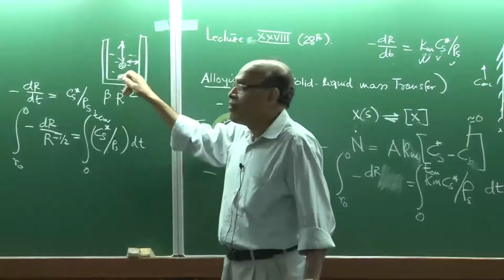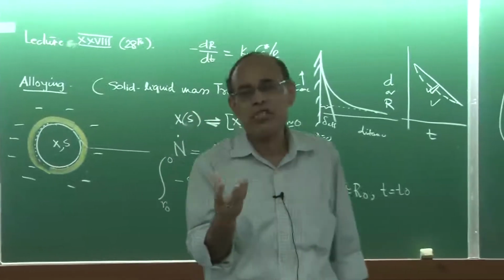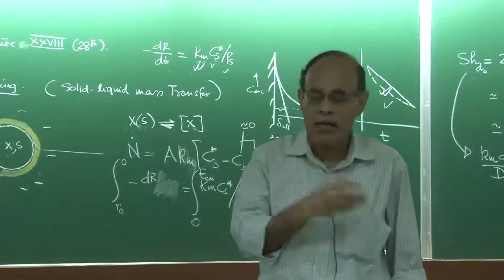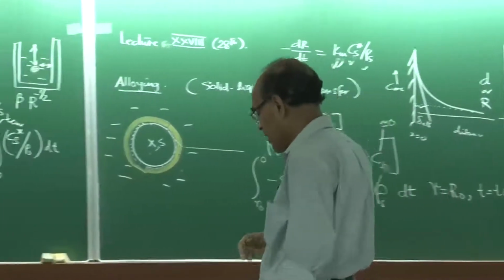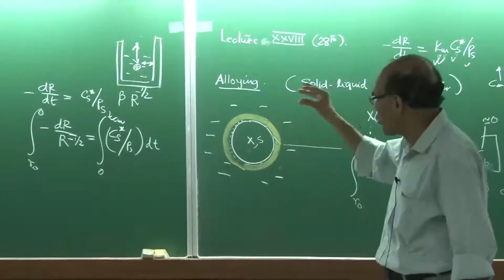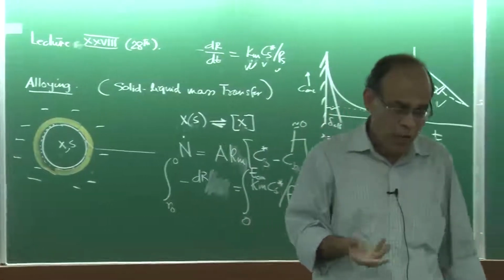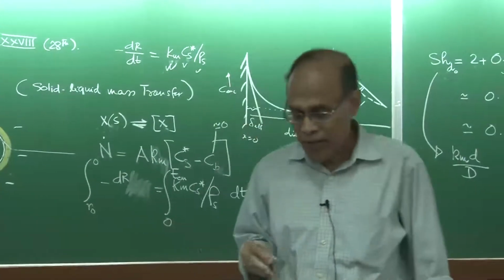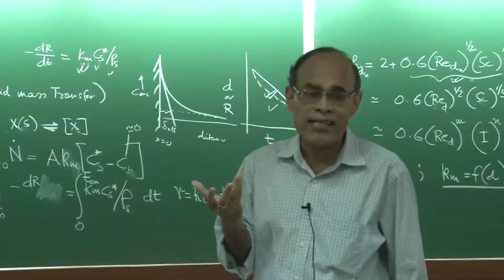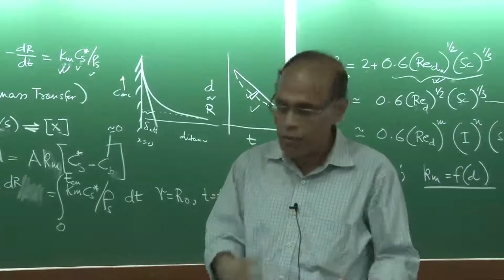So for a given size, typically we would be adding this size lump, which is about, I would say, a 25 millimeter radius. There's a 5 centimeter diameter or so, that is the maximum size of the particles. And when you add those solid particles, depending on the alloying additions, whether it is tungsten or niobium, etc., they can take something like 600 seconds, 700 seconds, which is about 10 minutes to dissolve into the bath under a moderate amount of stirring.